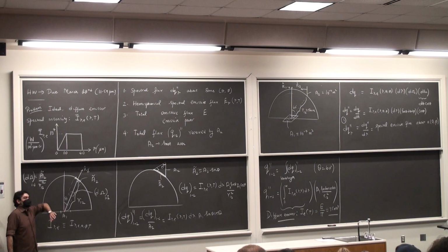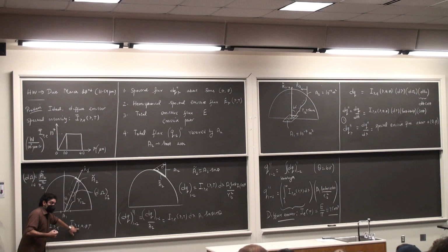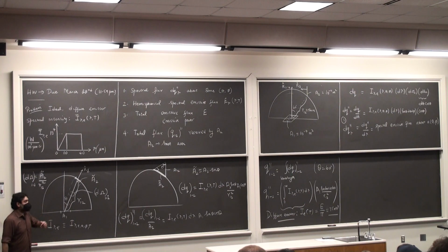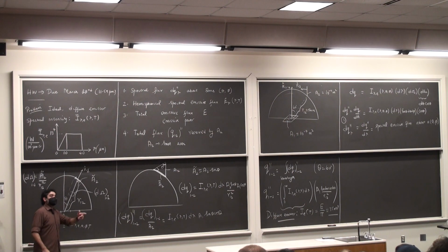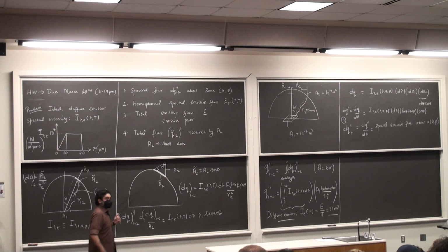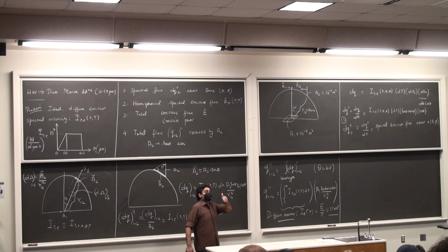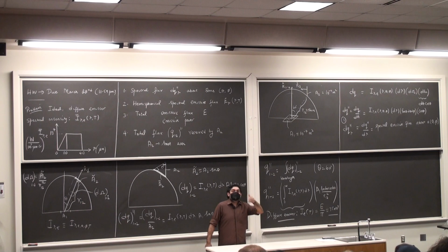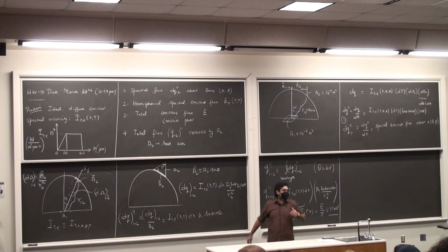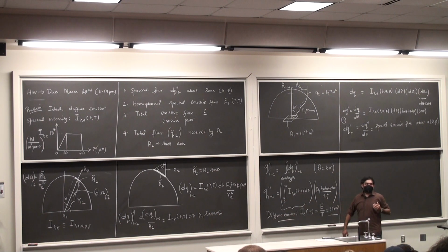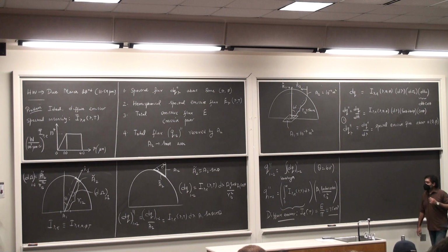And just to make sure we are talking about a quantity that is dependent on the spectral characteristics, you keep the letter lambda and you keep the letter E because it depends on emissivity. This is emitted radiation, emitted intensity. If it is irradiation, then the E will be switched to little i, which is the incident intensity. And if it is radiosity, it's going to be E plus R, because it's going to be some part emitted plus some part reflected. If you recall, we defined radiosity some time back. Don't worry about it. We'll come back to it again.